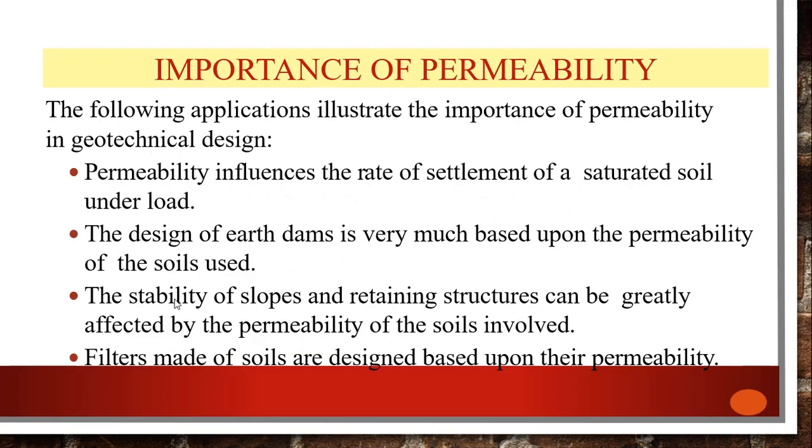Now, the importance of permeability. Why is permeability very important? Because the following applications illustrate the importance of permeability of a soil in geotechnical design. Permeability influences the rate of settlement of a saturated soil under load. The design of an earth dam is very much based upon the permeability of the soil used, because an earthen dam is made up of locally available material.